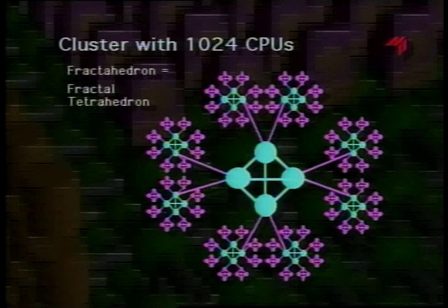So this is kind of a snowflake structure, and it can be used to scale the system into a very large number of nodes. In this case, we have a way of connecting 1024 nodes through a maximum of 10 router hops. By the way, if this were a fault-tolerant network, the entire structure would be duplicated, and every dual-ported device would be connected to both of the fabrics.